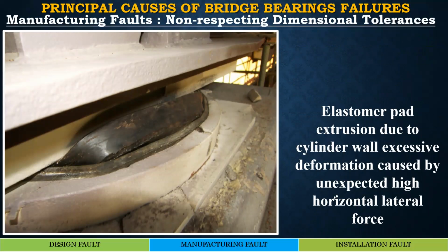There is also a possibility of the elastomeric pad extrusion when there is an excessive deformation which is caused by high horizontal lateral forces during construction. As I explained earlier, if during construction stage proper care is not taken, the bearing forces, lateral loads can increase to a very large extent, and that can cause failure of the bearing during construction stage itself, as you can see in this particular slide.